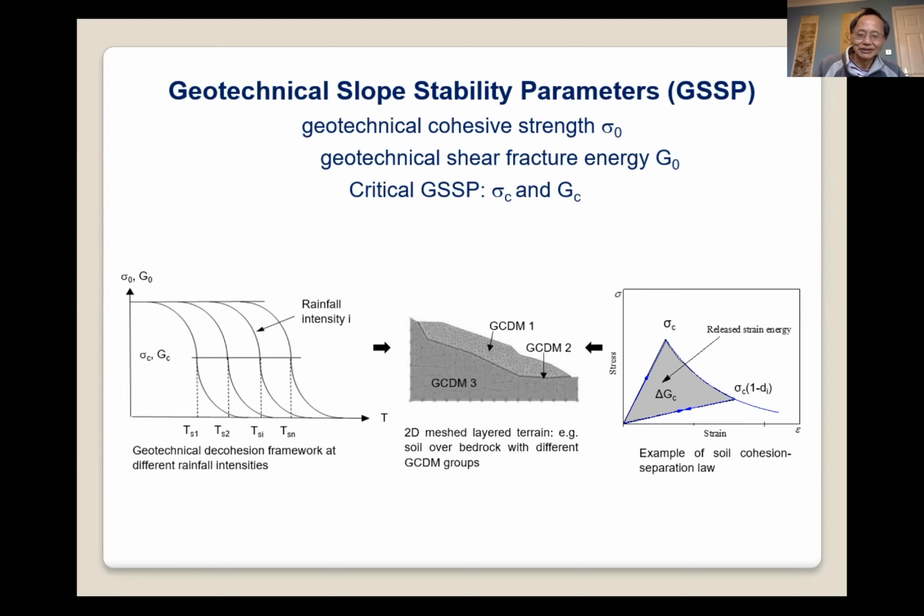Then we can predict the shear fracture as the landslide happens: which location, which layer, and so on. And also we can predict the shear crack propagation, how far it goes, the maximum distance moved by the landslide, which would be a potential damage size on the site.